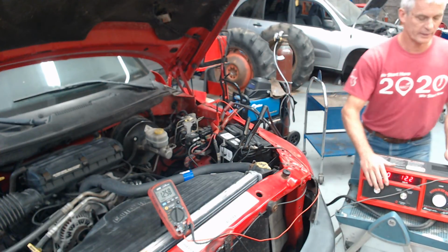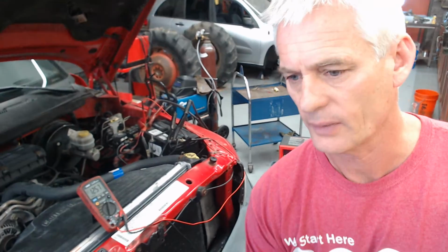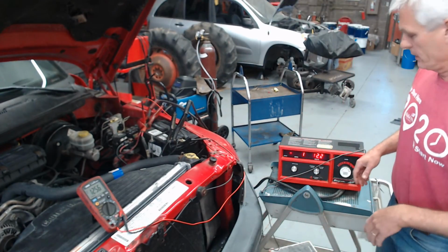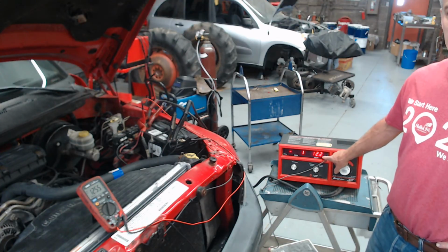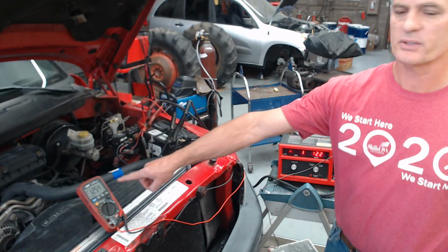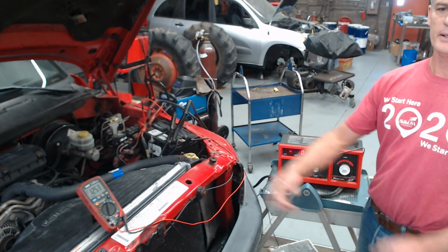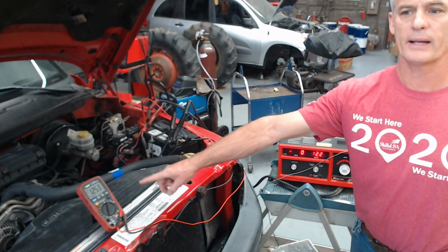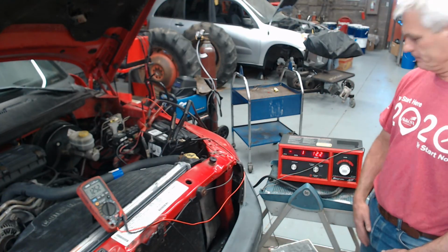Let me move the camera so you can see it just a little bit better. So if somebody was cranking the load knob, but you'll see this one's saying we've got 12.2 resting volts. This one says we have 12.54. You might ask the question, which one you're going to believe. This digital voltmeter is a lot more accurate than this in terms of voltage, but it's ballpark.